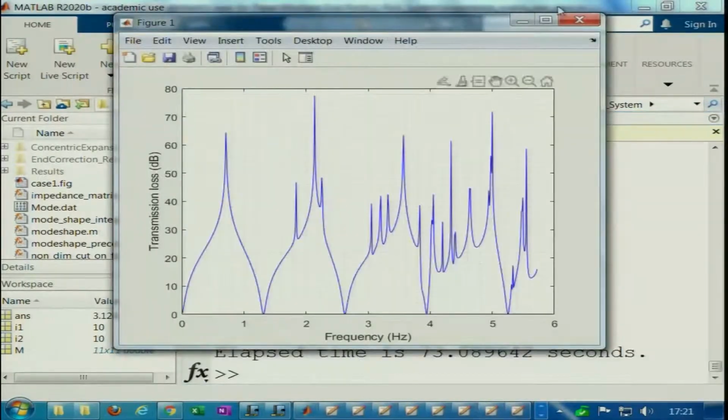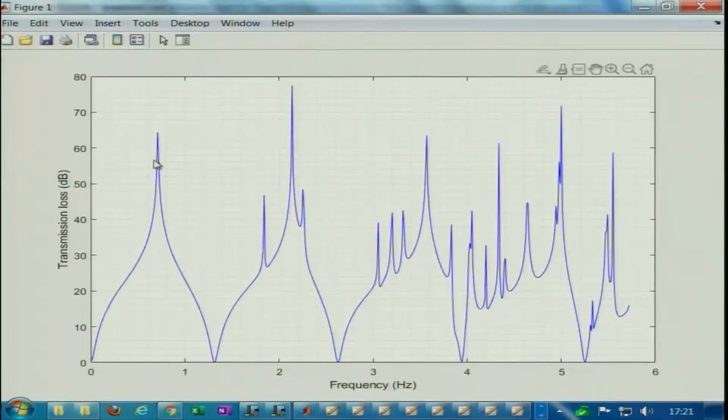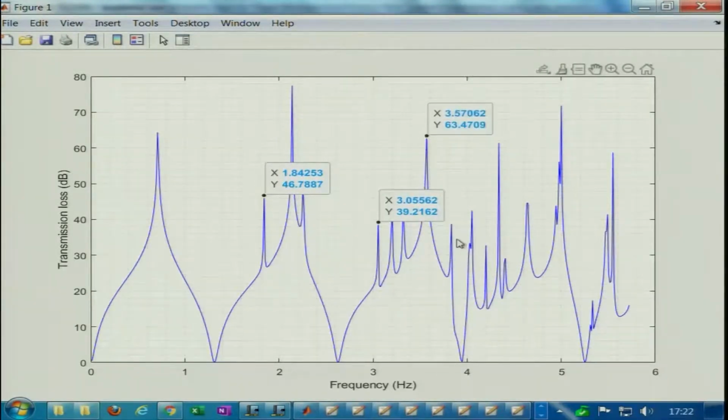So, we get the transmission loss characteristics of a flow reversal chamber. You see this is a peaky behavior. Instead of a dome and trough, now you are seeing an attenuation peak and a trough, and there are multiple spikes. This always occurs at 1.84 peak, and this is occurring at the cross modes, of course, and then you are getting a peak at 3.05, and 3.84, I guess, no 3.57, 3.84 somewhere here.